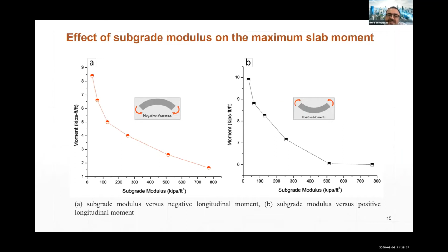So the effect of the springs, or the effect of the soil stiffness, is reported by making a flexible boundary condition or rigid boundary condition that can affect the load distribution from the trucks or buses to the ground. That is the way we see the differences and the significant effect in moment reduction or increase in moment when the subgrade is changing its characteristics.